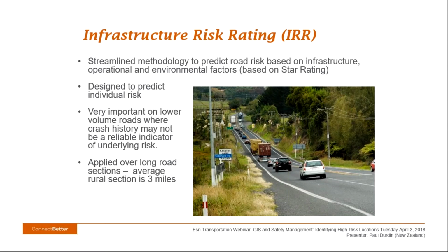In New Zealand, the star rating approach had been applied to 7,000 kilometres of the state-controlled network. And New Zealand wished to extend this proactive risk approach to the non-state highway part of the network, but the cost and time involved with star rating was seen to be prohibitive. So in New Zealand, they developed an alternative proactive risk methodology, which has been titled Infrastructure Risk Rating, or IRR.